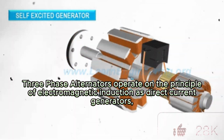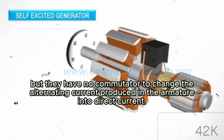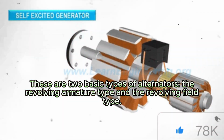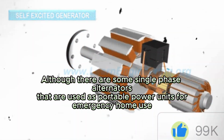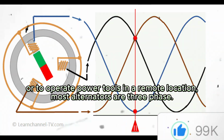Three-phase alternators operate on the principle of electromagnetic induction as direct current generators, but they have no commutator to change the alternating current produced in the armature into direct current. There are two basic types of alternators, the revolving armature type and the revolving field type. Although there are some single-phase alternators that are used as portable power units for emergency home use, or to operate power tools in a remote location, most alternators are three-phase.